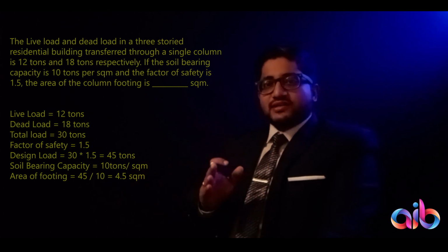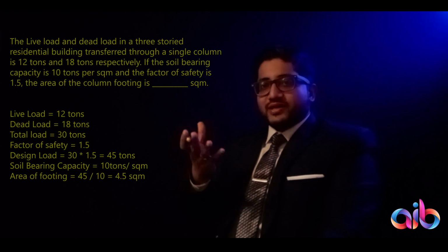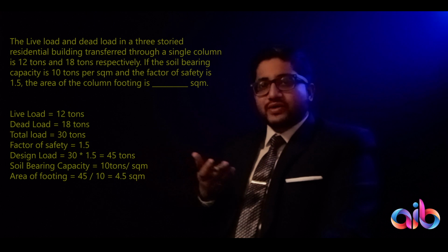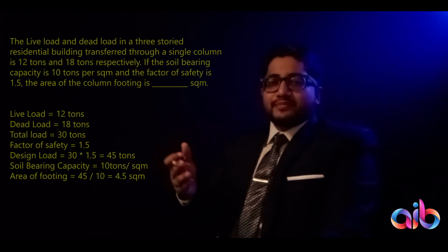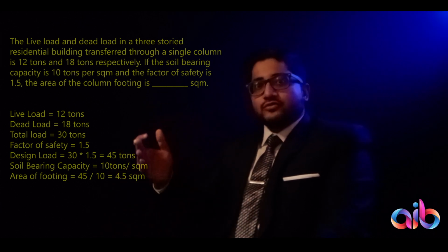So you would definitely need, now that you have 45 tons of load being imposed, if you're making a foundation, you would have to make it of an area of at least 4.5 square meters, because 10 per square meter, so 4.5 square meters would account for the 45 tons of load being imposed.